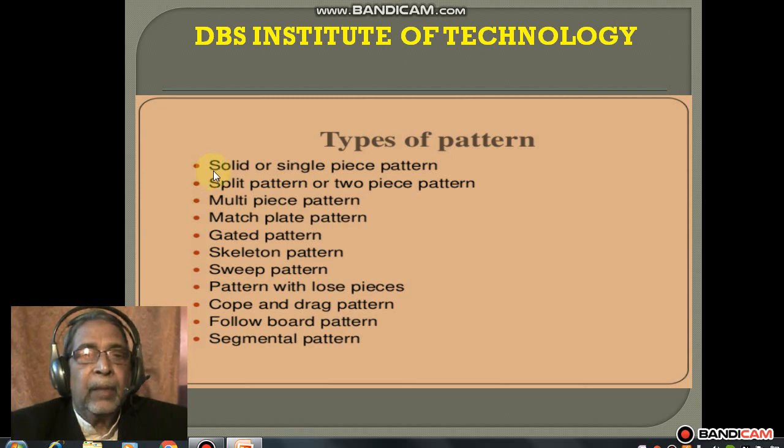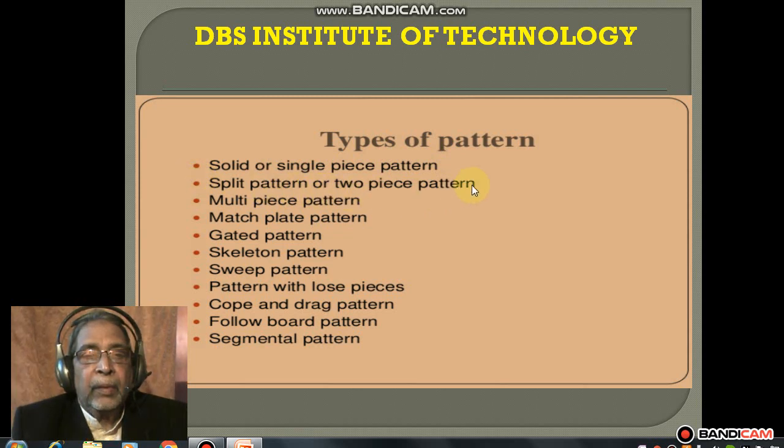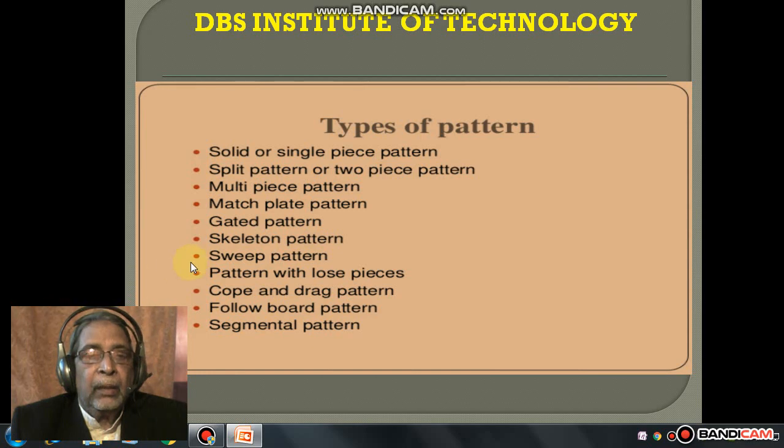It may be a solid or single piece pattern, or a split pattern or two-piece pattern, or a multi-piece pattern, or a match plate pattern, or a gated pattern, or a skeleton pattern, or a sweep pattern, or a pattern with loose pieces, or cope and drag patterns, or follow board patterns, or segmental patterns.